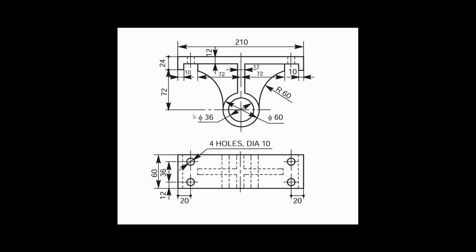Now we are going to create a 3D model by using these two different orthographic views. Here we have a front view, also the top view. If you see the top section of this particular portion, we get this top end view. In this top view, the visible lines, also the hidden lines, are shown at the particular portions.